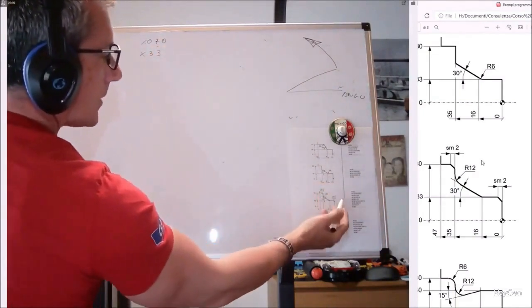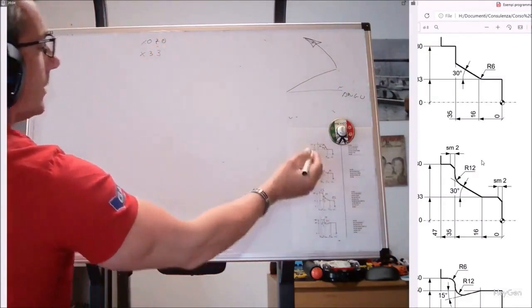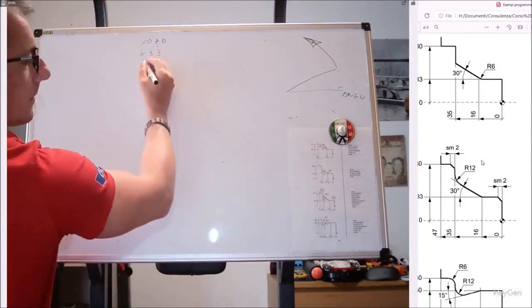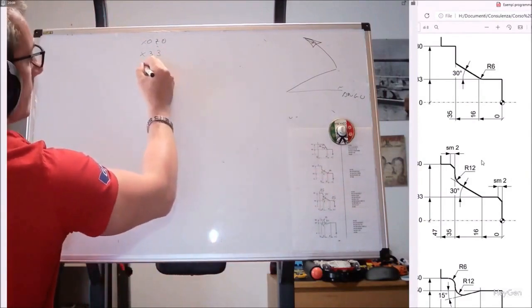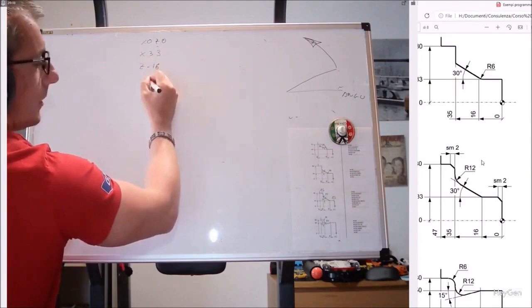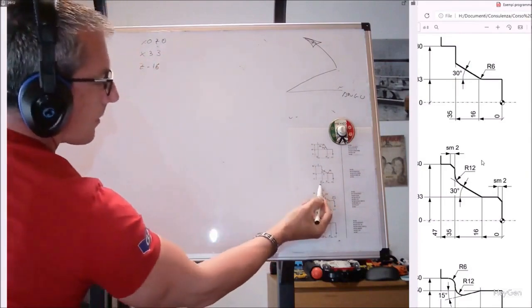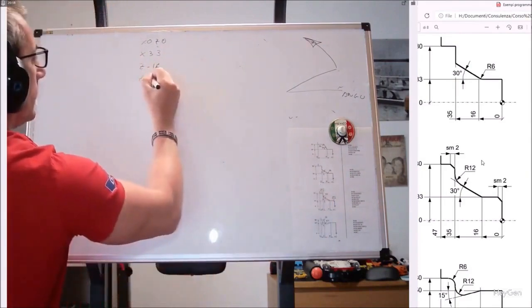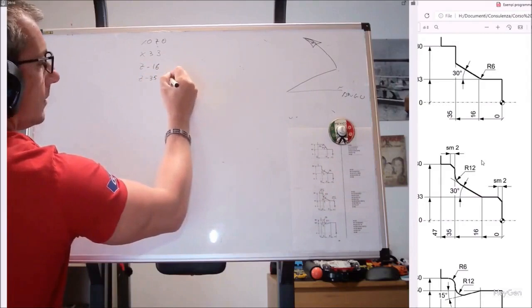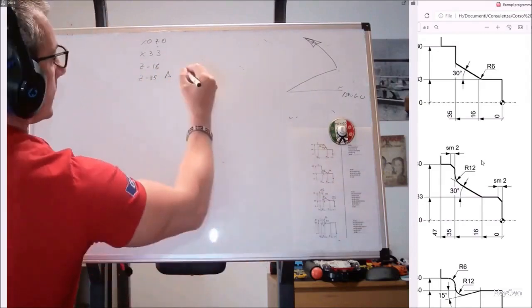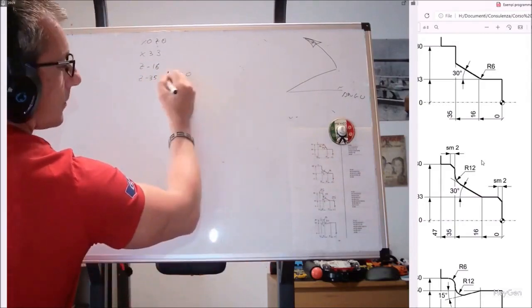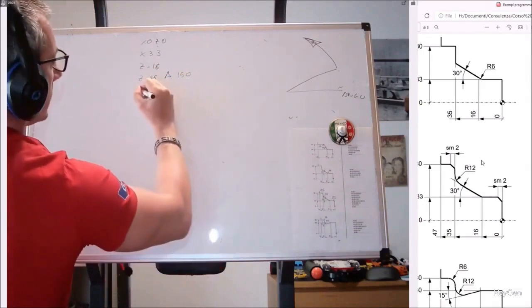And here, it is very simple. Just put a little corner once we are at X33. First we go to Z minus 16, and here, what do we put? We have Z, so Z minus. Angle 180, 30, 150, X80. And then the Z at that point is relevant.